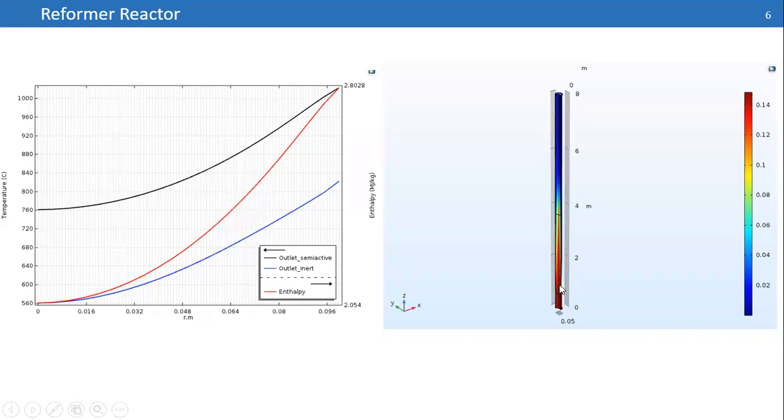But in this section, you reduce the activity of the catalyst by loading a lower amount of, for example, nickel on the surface of your catalyst, or any type of catalyst that you are working with. In the third part of your reactor, you have a highly active catalyst that has a higher content of active sites that can overcome the limitations of the previous sections. But for solving this type of reactor, which I can call a good example and a complex example,